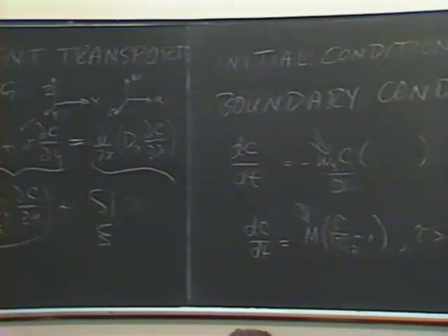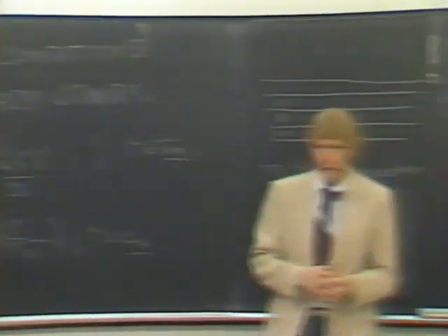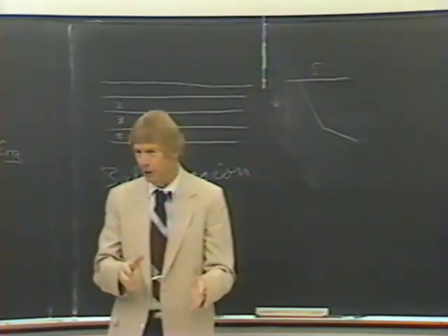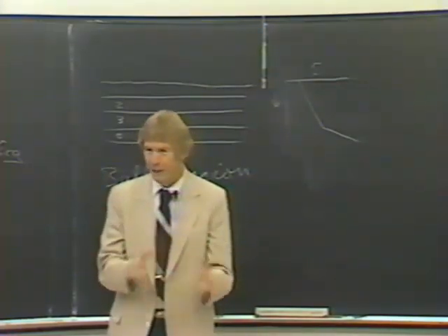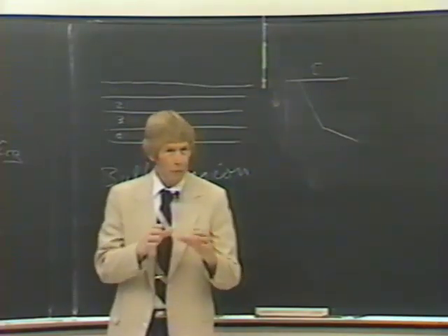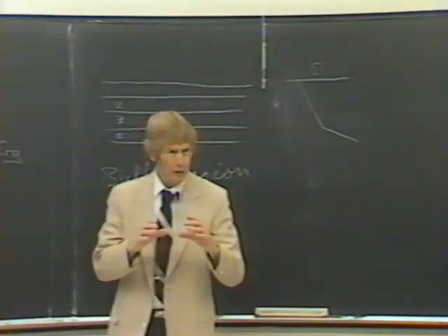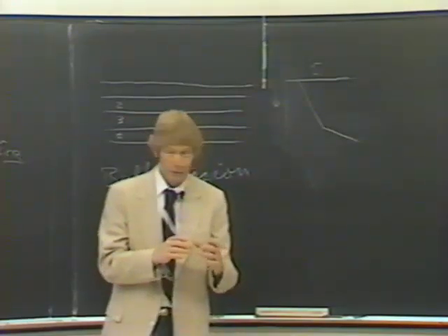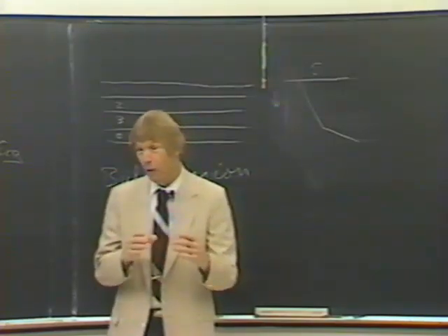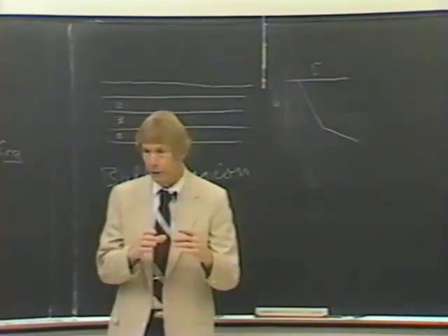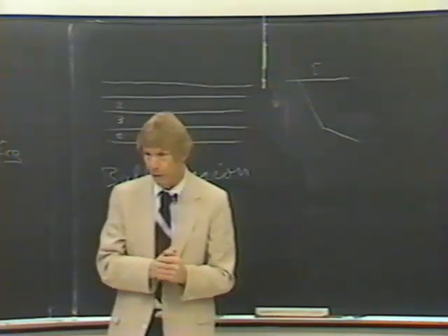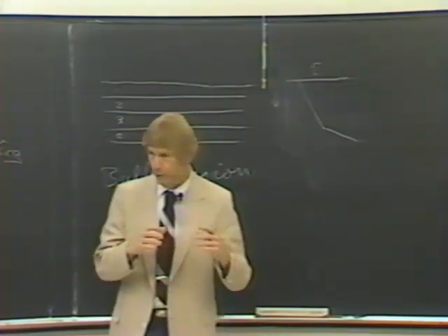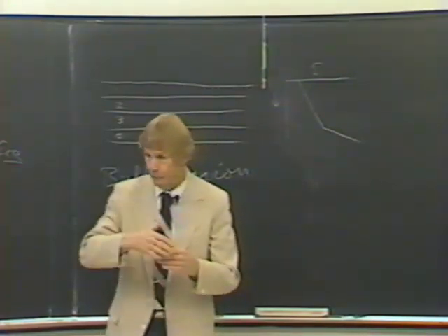I'll have to say something else about modeling while we're on it, because models are a little too easily accepted, in my view. You'll find that consulting firms will take somebody's model and put it on their machine and put all the information that the model demands into it and accept the results. The critical thing about modeling is visualizing the system, that is, knowing pretty well what the system is, understanding what the processes are, and then exercising the model. And it's a good idea to know what's in the model. That is, look at the source code and see exactly what's been done, because there are often some shortcuts in it. Then exercise the model using known inputs and known and expected outputs, that is, verify the model. Only after you're satisfied that the model truly represents the system that you're dealing with, try the changes, and then you're essentially extrapolating from an existing system.